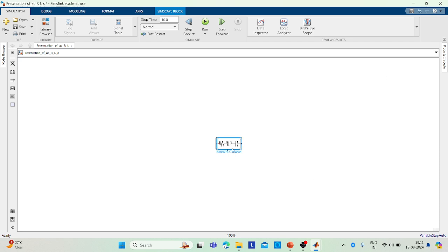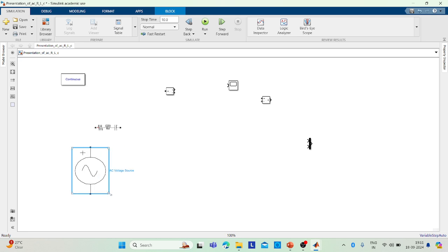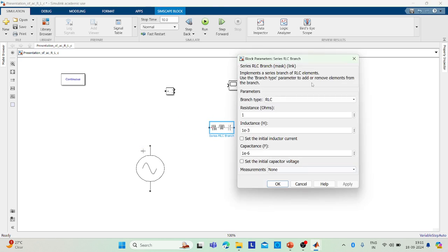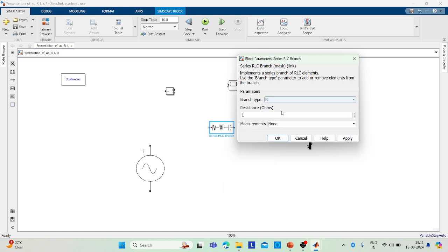Yeah. So here on this presentation, I have all these parameters accumulated at one point. So let me segregate them one by one. Okay, now I have this source voltage. So I am just elaborating the block, and I have an RLC branch. Let us start with a resistor first, and let me take the value of resistor as 10 as it is shown in the PPT.